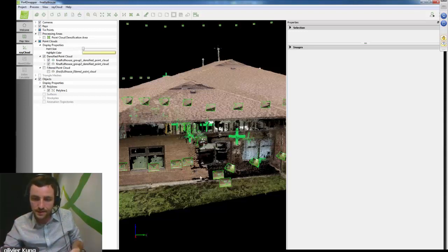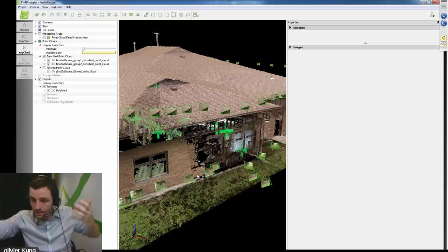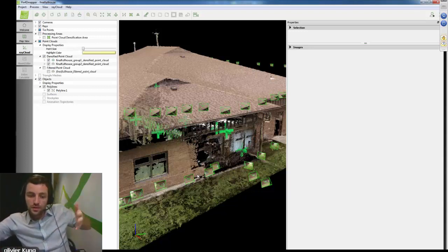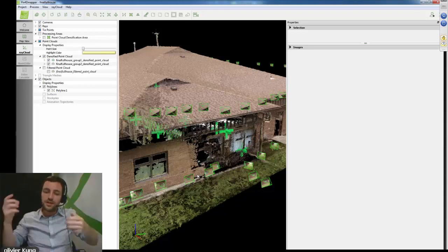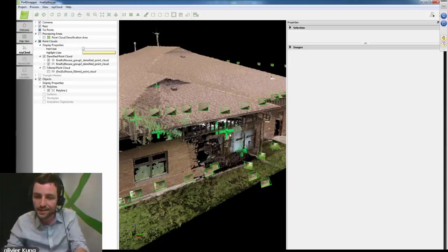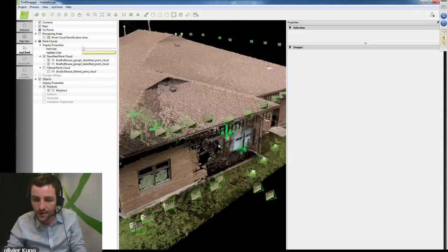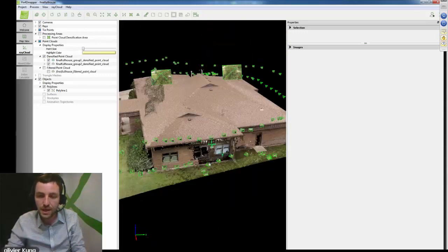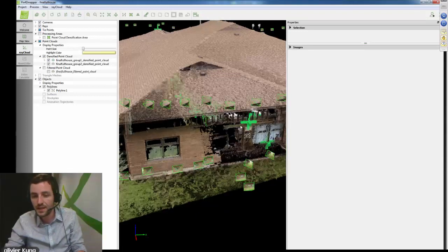So in that case, taking pictures very close is, I think, the recommended way, but then doing another set of pictures further away from the facade would make sure that you didn't forget a small part of the facade, like the user did in this case. By having another layer of pictures from behind the tree, maybe it would have covered that a little better. But this is mostly for practical reasons, not theoretical reasons.